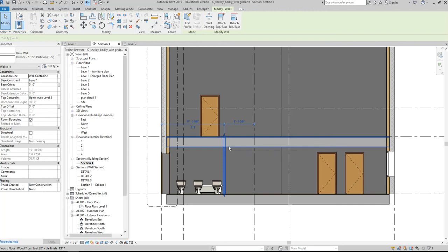I think this is another constraint that Revit allows. So if I had a bunch of walls on the main level, and there were 50 of them and they all kind of went through the structure, and I said, yes, attach it to the bottom of this floor, they would all then attach themselves to the bottom of the floor. And so if the floor moved and I didn't want the walls to move for whatever reason, now those are sort of glued to the bottom of that floor, regardless of what happens to the floor. So at first I thought, oh my gosh, that's amazing, right? So I'm going to start doing that. And then I realized after a few hits and misses that it wasn't as magical as I thought it was going to be. And so I stopped doing it.